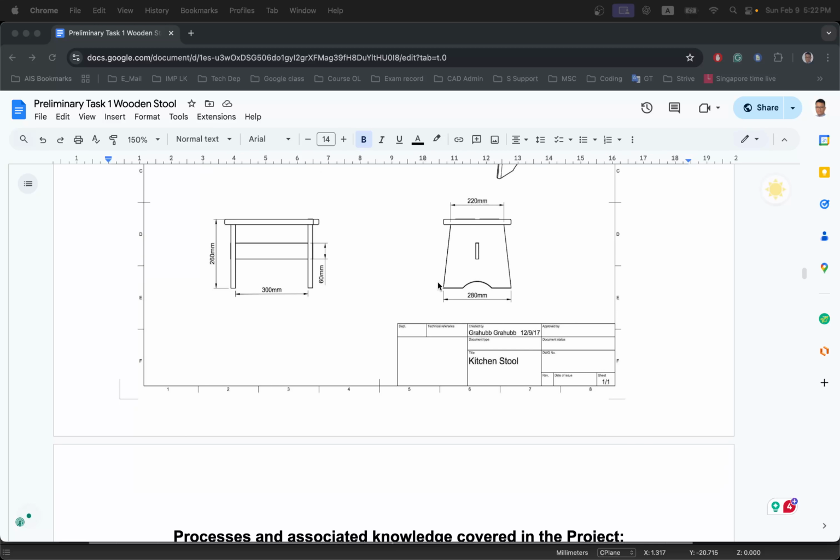If you have turned on the midpoint snapping, you just call the move function, M-O-V-E, move. Here, press spacebar, allow your mouse to snap to the midpoint and move it over to the midpoint as well. So in this case, these pieces are now snapped to the midpoint,